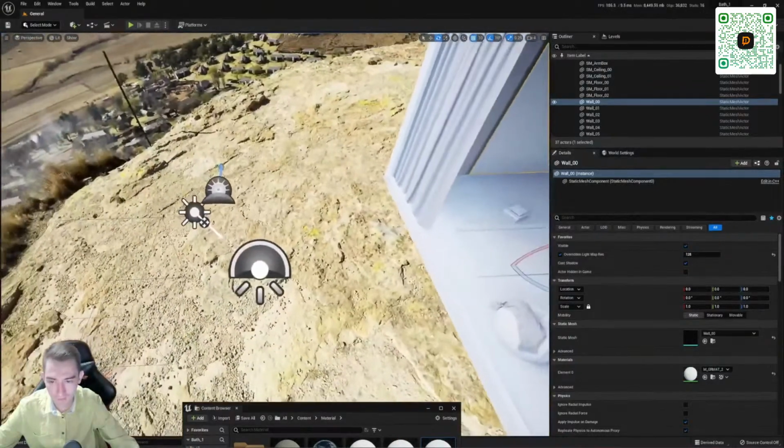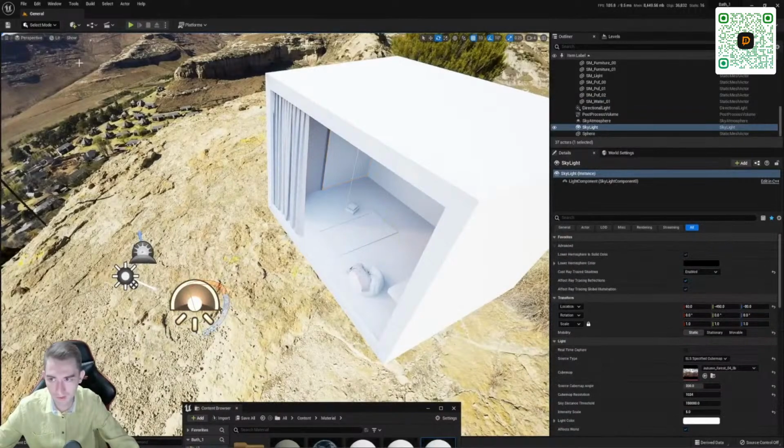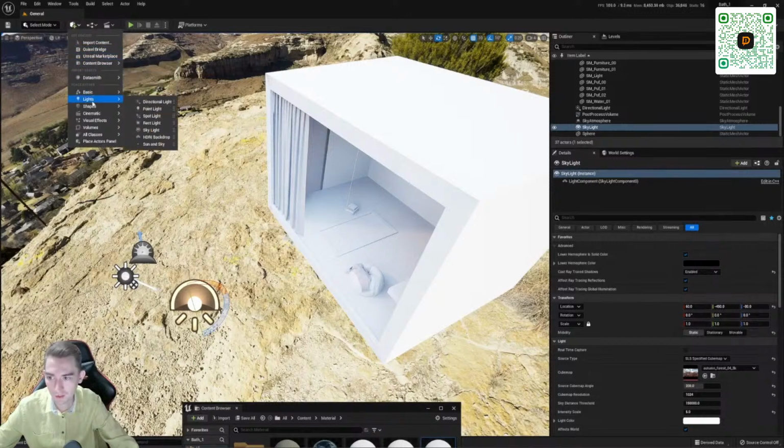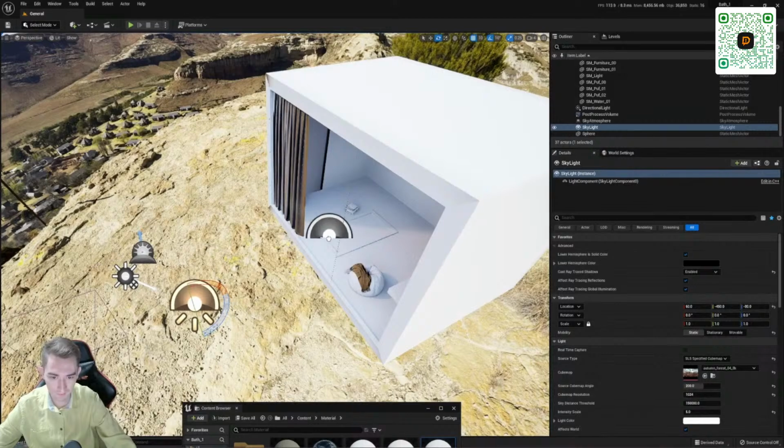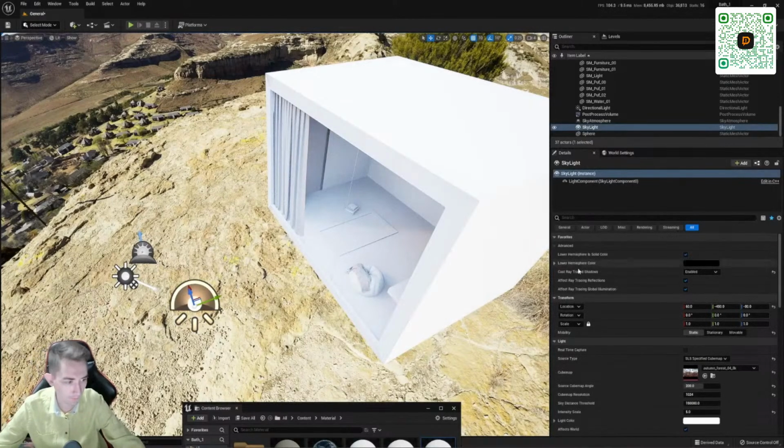Here I have the light set up very simply. The usual skylight, we create it through the create plus sign, where we create various actors, objects. Click on lights, and here we have a skylight. Just transfer the skylight and set it up. Now I'm going to show you what settings I used. First of all, here we set the static mode, since we will bake the light.